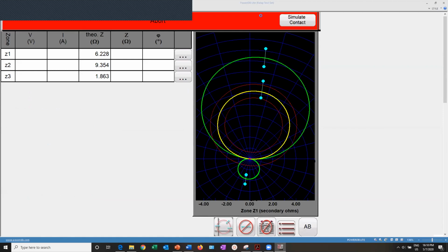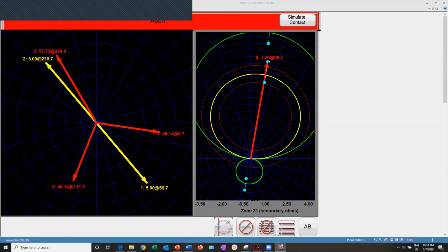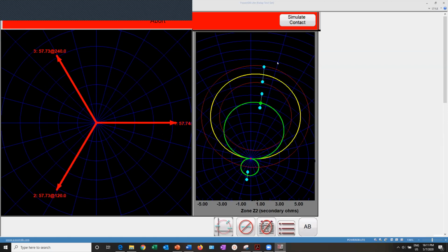If I click here, I will be running the three faults one by one, starting with this one on zone 1. What it's doing is using this line here, and along this line, it's generating different faults, and each of these faults is being injected for a time that is shorter than the time it takes to trip on zone 2, because all these faults are actually in zone 2, but since they happen for a time shorter than the time to trip on zone 2, you shouldn't trip.